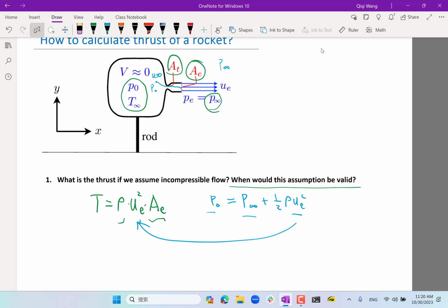So in this case, let's start thinking about the Mach number. Inside the plenum, the Mach number is equal to 0, so that's the easiest thing to figure out. What is the next Mach number that can be figured out? If the whole flow is subsonic and inviscid, we can assume the whole thing is isentropic. So based on isentropic relationships, what is the easiest Mach number to figure out in the whole system? The Mach number at the throat? How do you figure that out?